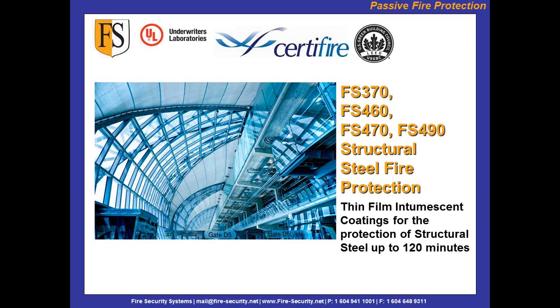That's why you will find on our certificates, for instance, that you will have an HP/A value and a dry film thickness next to it. Once we, or our estimators, work out the factor of that steel section within the plans or the specification or the scope, we will give you that section back with a dry film thickness plus a spread rate to achieve that dry film thickness.